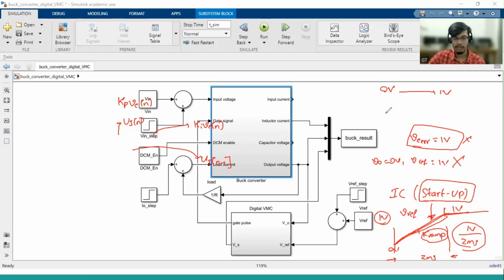When it is in sleep mode, nothing is being done. Say it is at its low P naught operation, and when you click or turn on the phone, it will trigger something and it will have to turn on. Say you are opening a game or any browser, it needs some current. So a buck converter has to give some I naught. It will not do it directly. This is one of the startup logics, and it does not have to be the only startup logic. They will make the startup logic in such a way that it is smooth and does not affect the full system.